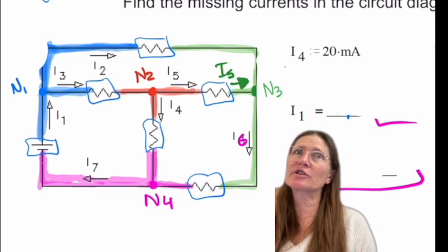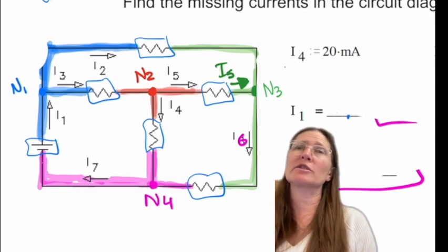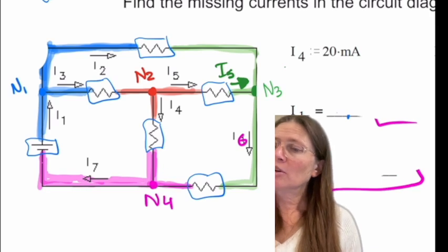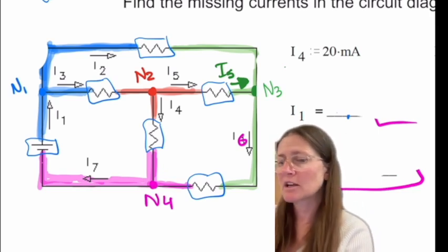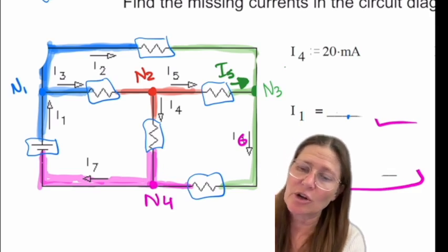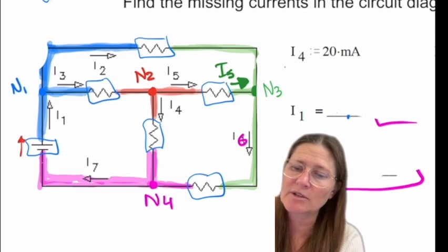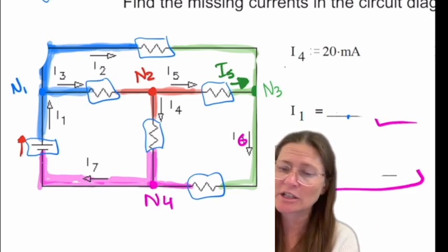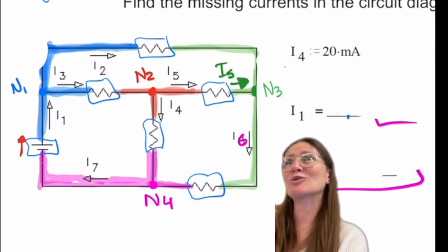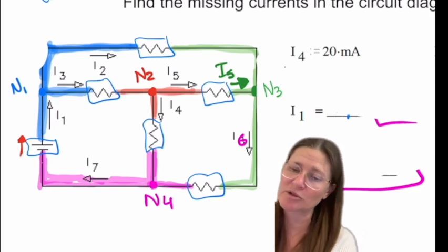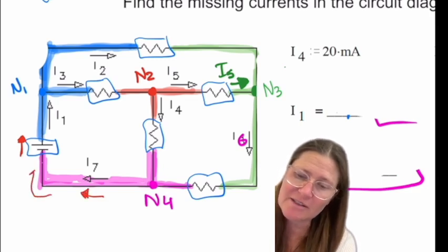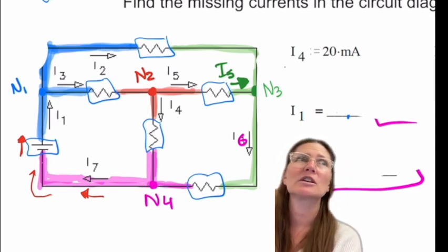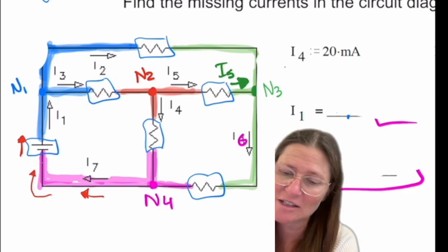So with that, then you look at the currents that are going in and out of the nodes to be able to do the current summation. So every element is where you're going to draw the current. So if it is not labeled, you're going to make an assumption of the direction. And there's no right or wrong assumption of the direction. So I can already see that there's some labels already in here. So I'm going to stick with whatever direction. And since they're both basically flowing in this direction, another visual thing that you'll have to get used to is the bend in wires. So I know it looks weird, but that just means that the flow continues in the same direction it was labeled. So if I label on this wire in this direction, it means it's going to continue around that corner in the same direction. So that takes a minute usually for students to understand that concept.